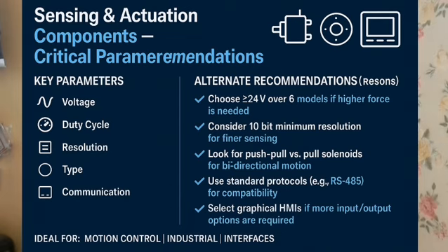Response time is also equally important because it's required for locking, injecting, and valve usage. Encoder resolution is PPR or CPR, so pulses per revolution and counts per revolution. I need to share more insight on it, but it determines the position accuracy.